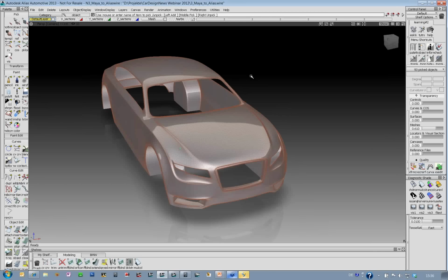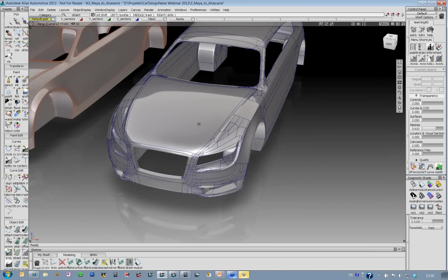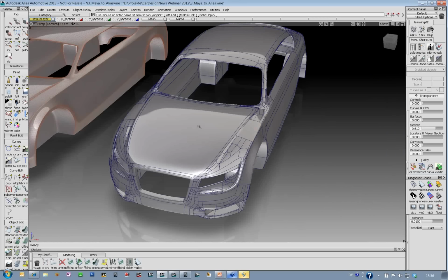The second approach is to convert this geometry into NURBS. You can see the NURBS model here. It's not the perfect layout, nobody tells it is, but in this phase it's enough for me to add some specific features on my model, because as I mentioned, in Maya I'm modeling the complex shapes, the whole car, not from gap to gap. And especially these gaps are something I can easily add on a NURBS model. Simply project the curve, panel gap, and it's done.